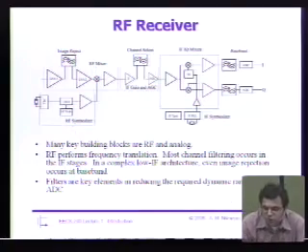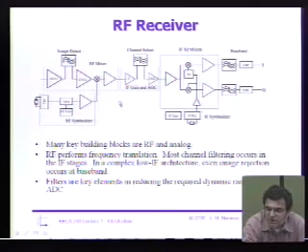If we look more closely at a block diagram of an RF system, what we call the RF stuff is here. Here we do some amplification with low noise, we do some frequency translation with these mixers, and we do frequency synthesis with this VCO. These are nonlinear building blocks.